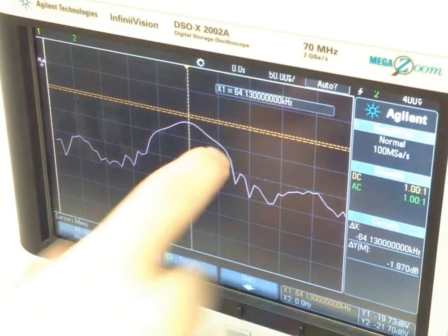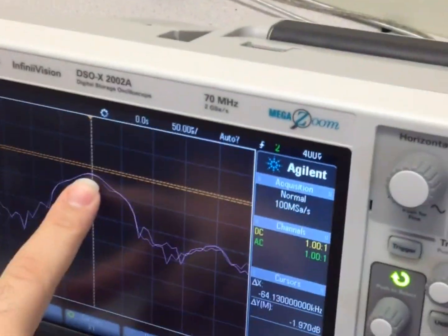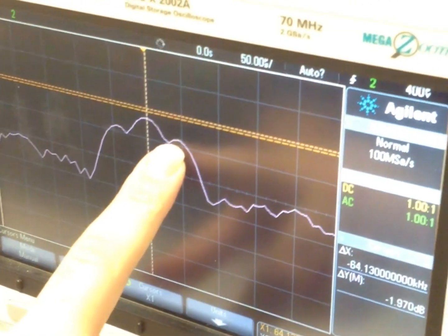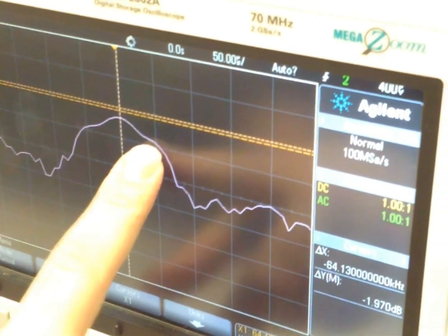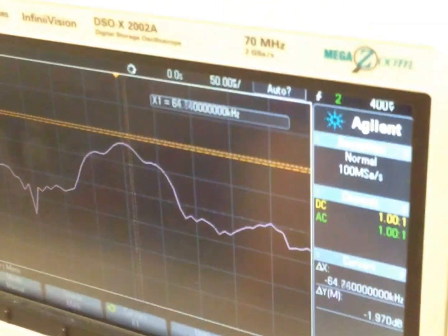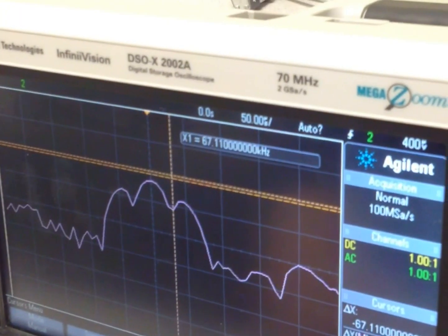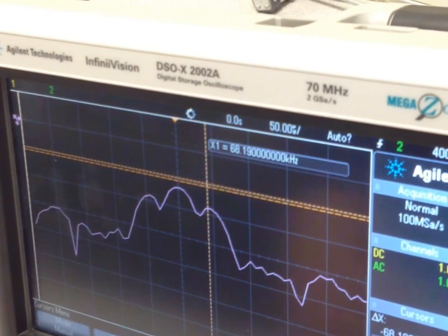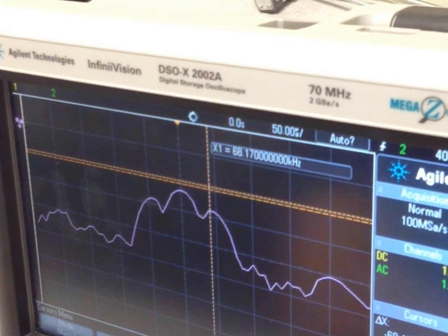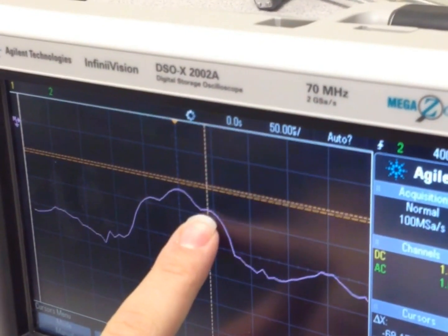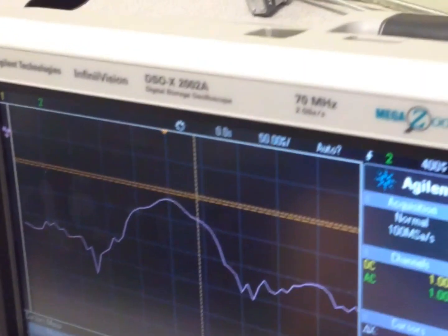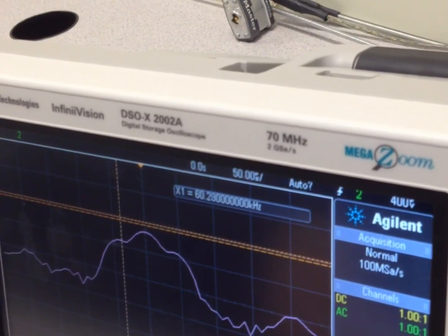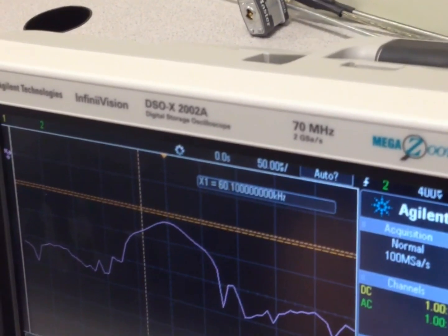Oh, so first of all, this is the amplitude of my carrier. My message is very near. Actually, you could hardly see the amplitude. It is here. It is 4 kilohertz before and 4 kilohertz after. So if I'm here at 68, you could see the amplitude now. It appears, but it is not so obvious. Or at 60 kilohertz.